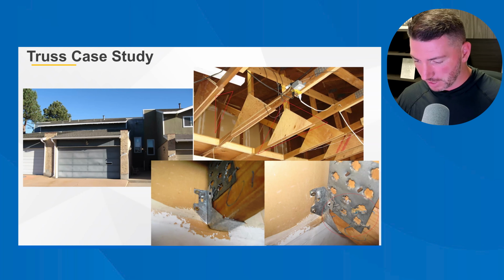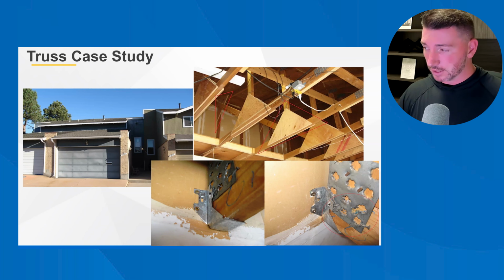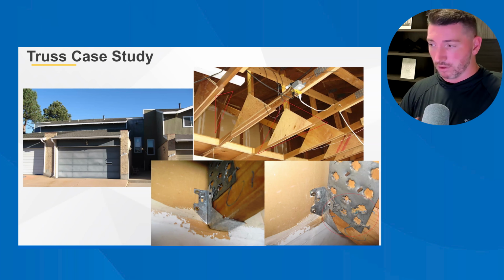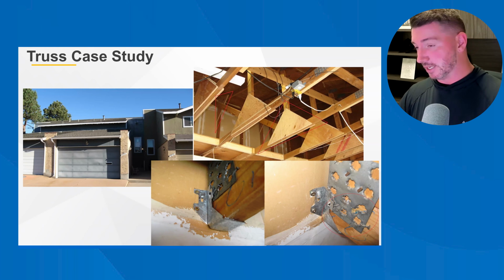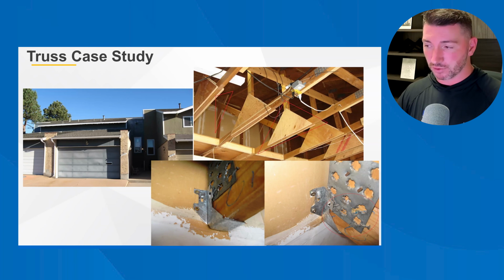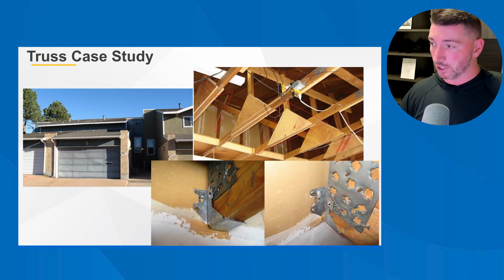The deck screws are a major defect because they're rated far below acceptable hanger nail strength. Remember that. Not all screws are created equal. Simpson makes all these connectors for different applications, and Simpson has their own screws to use for their own connectors because they're rated for a certain shear strength. These little gold screws look like interior screws. They don't seem to be a load-bearing thing. They're just not designed for that level of pressure because they're going to want to shear off.